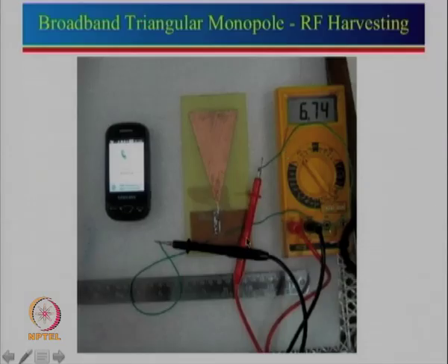have also put a load across these 2 points. So depending upon the load value, suppose let us say we put a load of 4.3 k, this voltage drops to approximately 4 to 4.5 volt. So you can see that typically 5 to 7 milliwatt power can be generated through this particular RF harvesting. In fact we have used an array of this also to get a larger voltage.